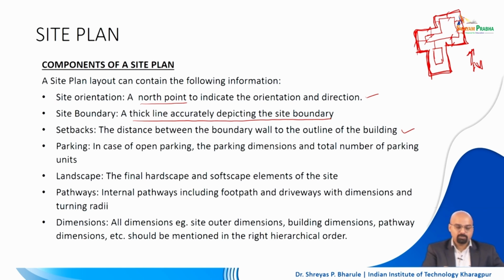Next, you need to show your parking. So, in most cases, if it is a bungalow kind of a structure which you are proposing on a large site, or even for that matter any kind of building which you will propose, you will have either open parking or you will have a covered parking, right. So, in case of open parking, you really need to show the parking dimensions which are there, the number of cars which will be parking in that particular location. Also, you need to mention how many parking bays you have.